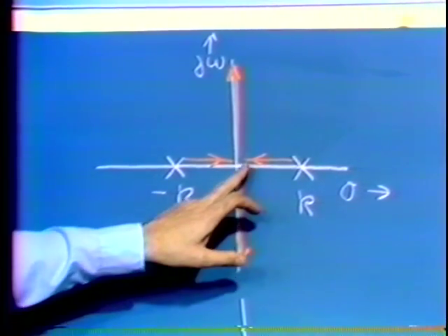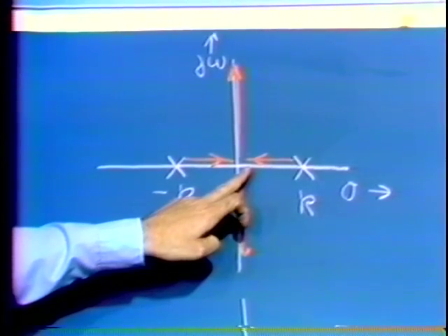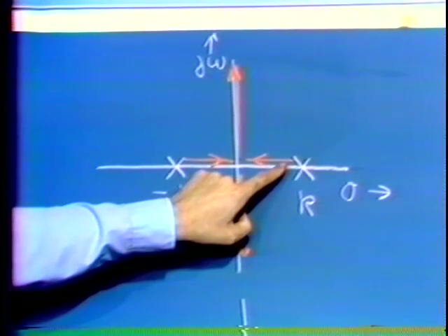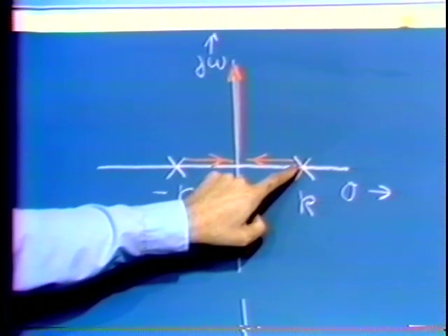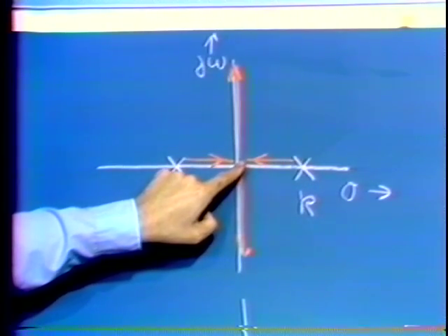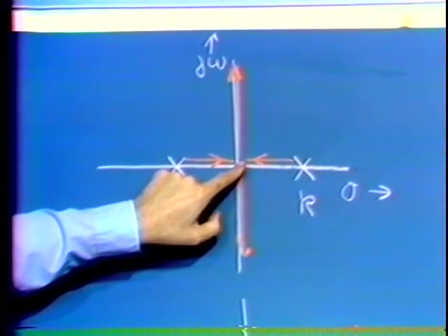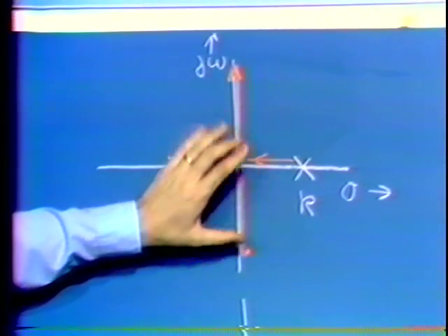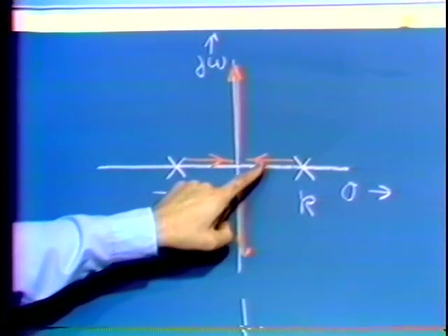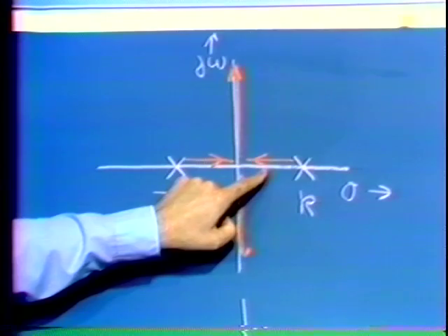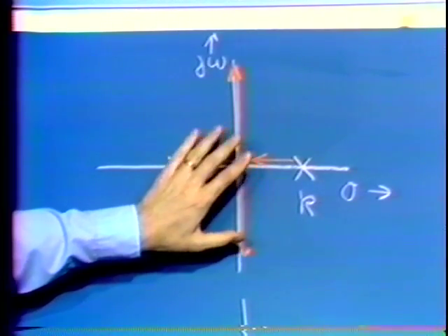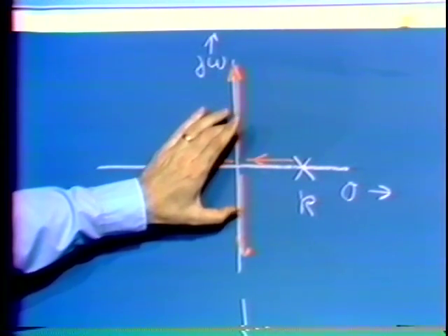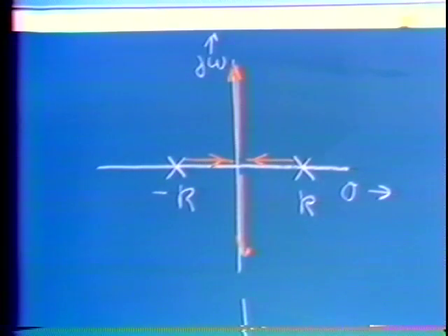So as we increase the gain of our amplifier A, one pole, the one that's giving us the difficulty, would move from its position in the right half plane and finally reach the imaginary axis. However, as we further increase gain, we then get a complex conjugate pole pair on the imaginary axis. The implication is that while we would have lost the exponentially growing response, we'd end up with an oscillator. Once we have sufficient A to get the closed loop poles out on the imaginary axis, the system describes an oscillator.